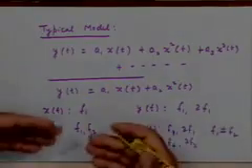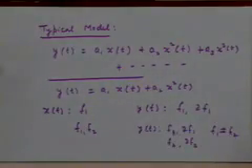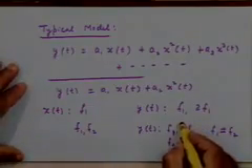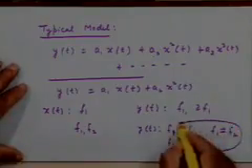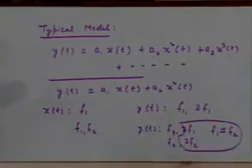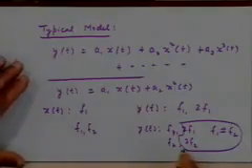You can see that. It's a matter of just writing down the trigonometry and seeing that you will get terms which is cosine of 2 pi into f1 plus f2 times t and 2 pi f1 minus f2 times t. So these additional frequency components that are getting generated is the real problem in nonlinear distortion, right?